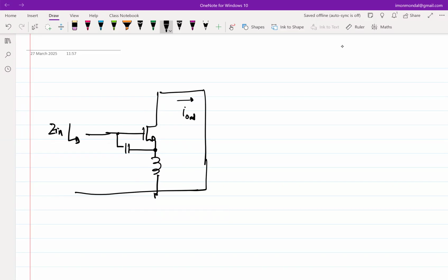If you just put an explicit 50 ohm resistance, it is going to have a real component, but that gives you additional noise, right? Additional power, the moment you have a lossy element, it is going to consume power and it is going to give you some noise. So if you have an explicit resistor or a resistor mimicking device, then you cannot really do much better than 3 dB noise figure. So then the quest was, can we think of something which gives you an equivalent real impedance without using an explicit resistor?